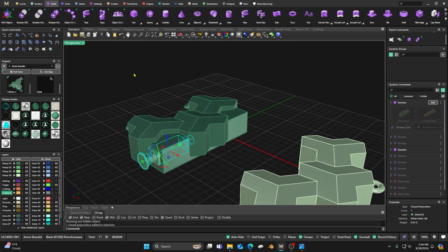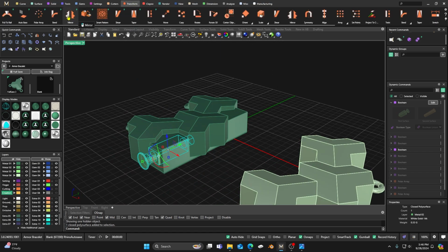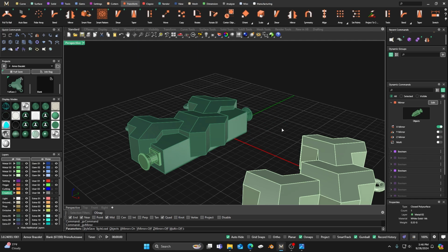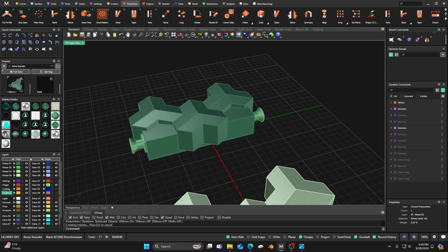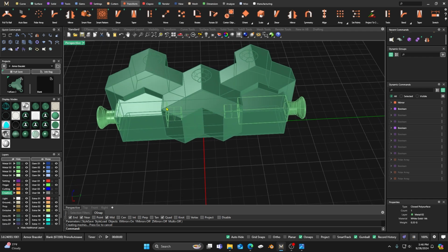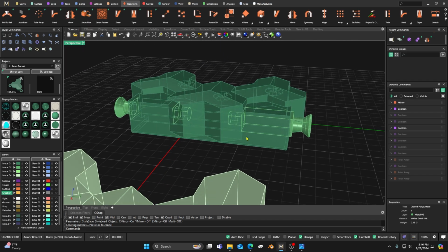And if we take this and we go to transform, and just to check, this is your final piece here, and we'll go to X direction, and then click. And then what we want to do is go to maybe a ghosted mode here, and we can see that the spring will come from here to here, pushing out, right? So that these will pop out, but there's no way to stop them just yet.